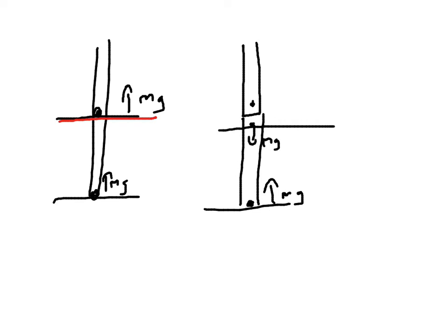So on this pin, imagine that's your whole floor. On this top pin, you're going to have the weight of the bottom platform plus the weight of the top platform, so it's needing to support twice the weight on one pin, which is obviously changing the way the forces are acting, and probably exceeding tolerances in places. So you've got to be aware of where the forces are acting, the magnitudes of the forces, how you're using them, and the materials you're using. Are they suitable for what you want to use them for?